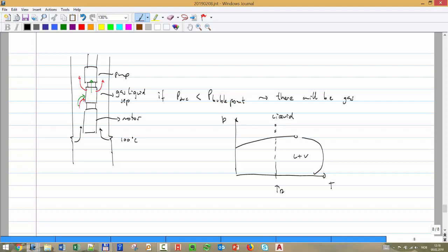But remember, if I have this gas flowing through the annulus, I have to have a way to take it out of the well. If I continue all the way up, this is not up to scale, I have to have a way to drain that gas, to produce that gas. So I have to make a hole here, put a pipe and a valve, just to be able to produce the gas. And that's not really typical in an offshore field. You don't produce gas through the annulus.